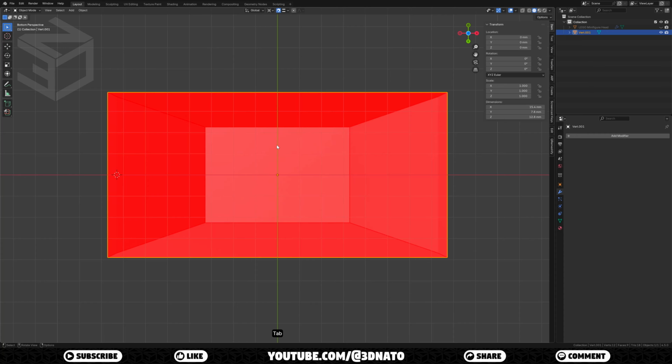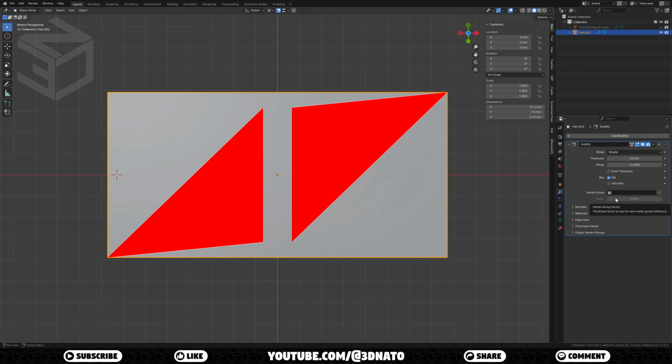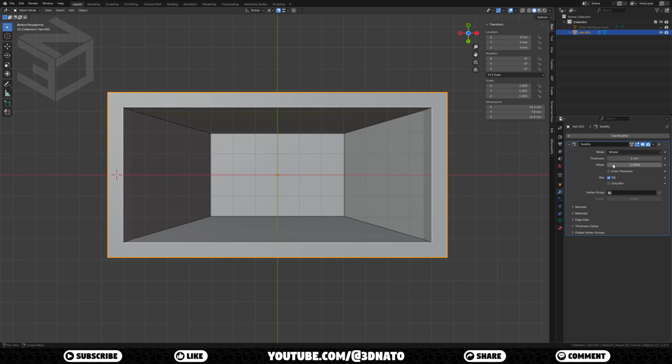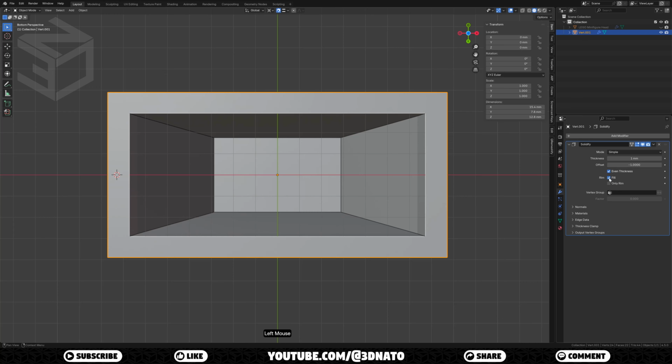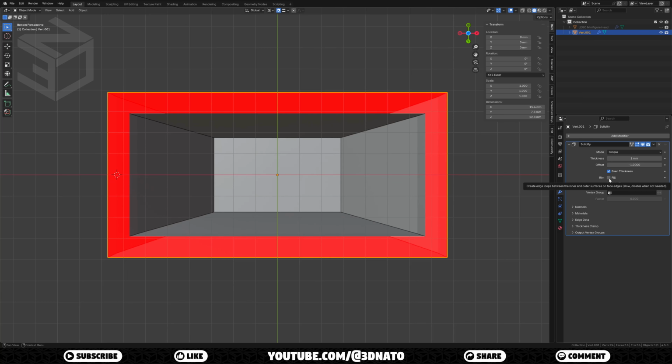Now let's add thickness to this mesh. On Modifiers, Add Modifier, Generate, and add a Solidify modifier. Set thickness to 1 mm, offset to -1, check Even Thickness, and uncheck Fill. Now press Ctrl+A to apply the modifier.